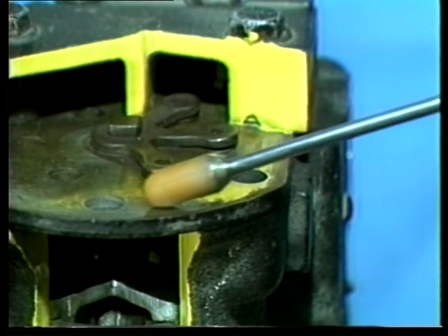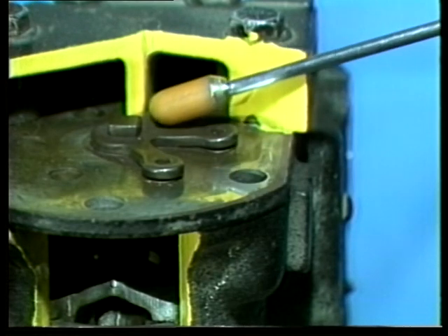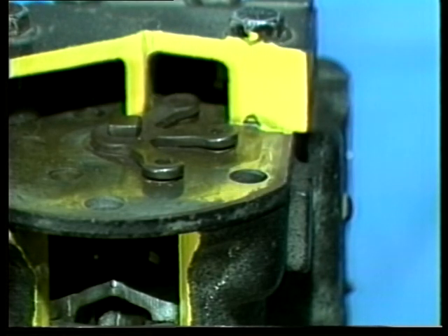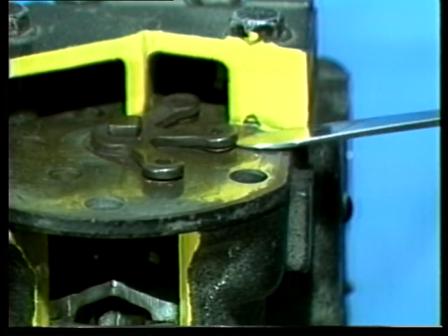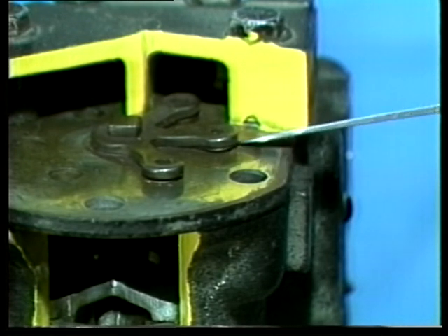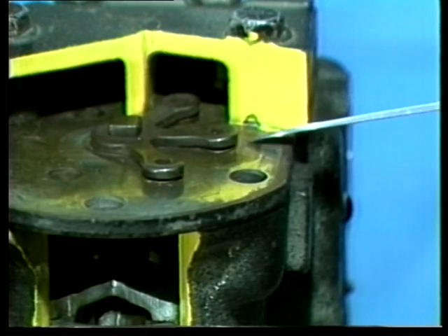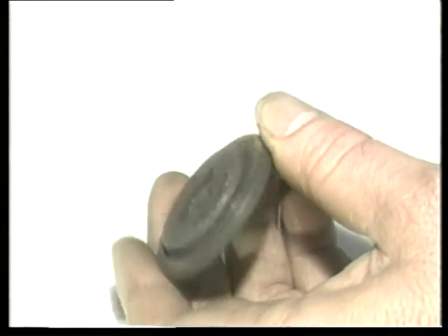Reed valves are one-way valves that make the refrigerant flow through the compressor and system in only one direction. This is an older style reed valve. Note how it has a thin steel flexible membrane or valve. The plate will flex open to pass vapor in one direction, but flex closed and seal off the opening in the other direction.